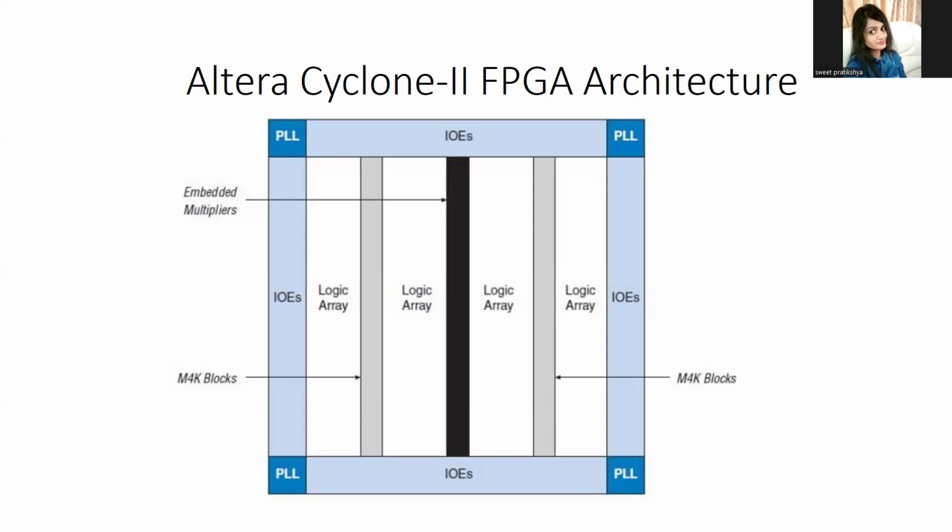So coming to logic array block, in short we can call it LABs. These are the fundamental unit. Inside each LAB are the logic elements and inside those are lookup tables. We know lookup tables contain the truth tables and the flip-flop will store the binary data across the clock cycle. Also the LUTs will contain the combinational logic blocks like AND gate, OR gate, etc.